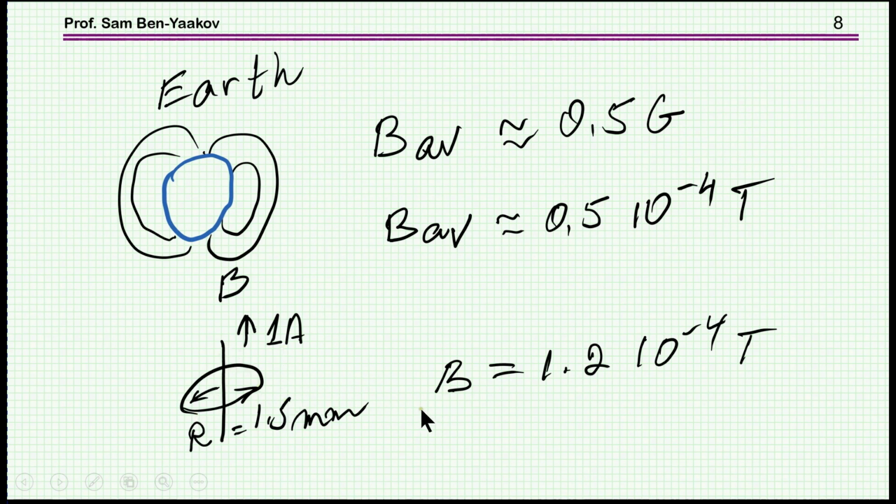But again, we're talking about small signals, and there's a problem of interference from, first of all, the magnetic field of Earth, and then if you have some circuits, magnetic elements, inductors, transformers, etc. around it, there might be a problem measuring the magnetic field in order to get a measure of the current.